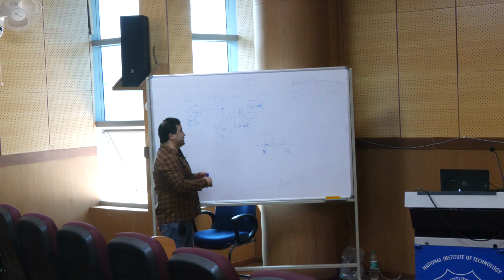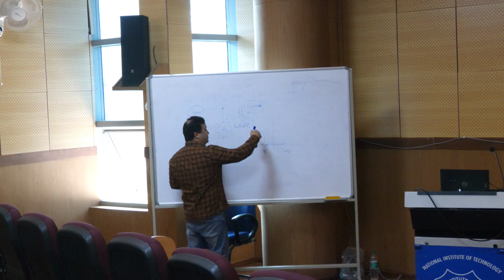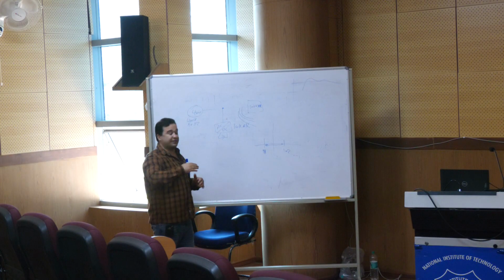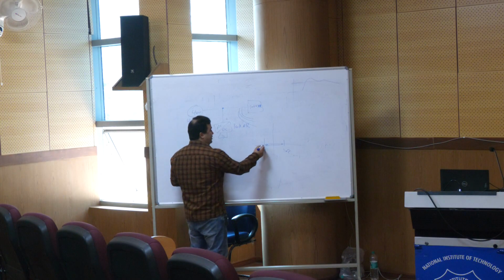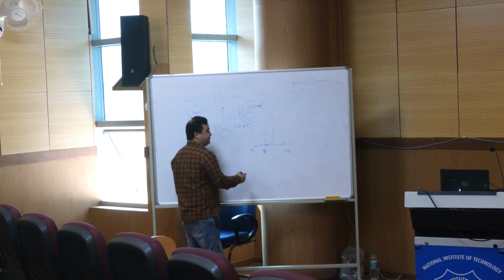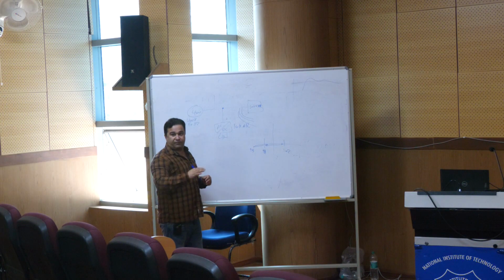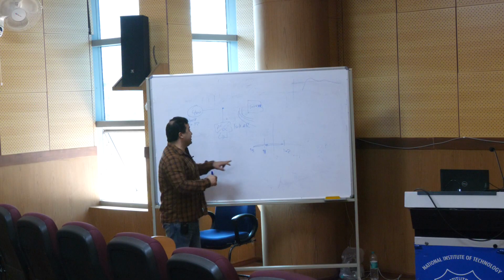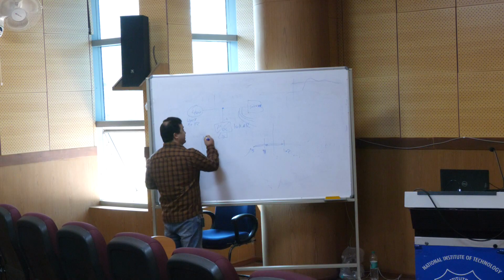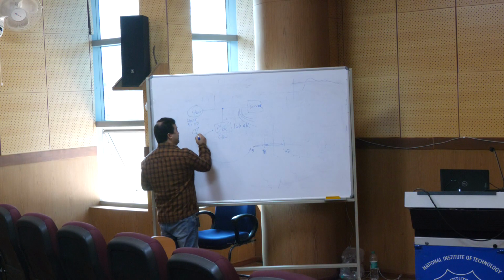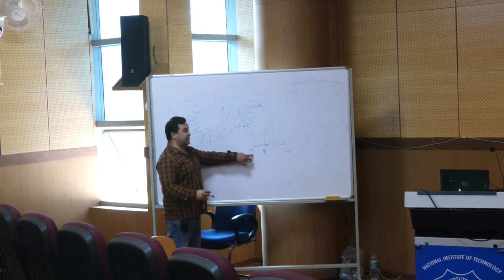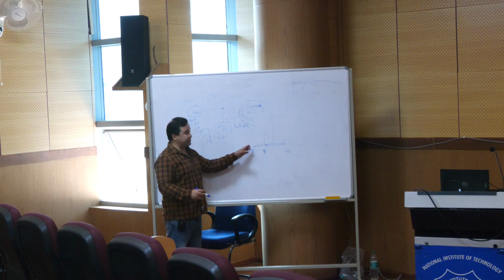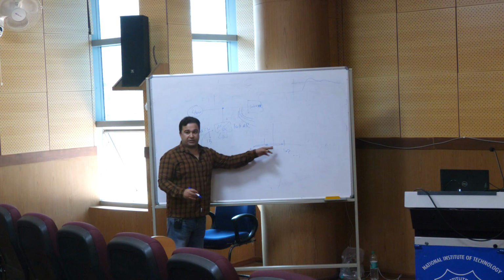But when we increase the reactive, for example, two times or several times more, then the voltage goes to, for example, 95. It drops 5% instead of 2%. So we need to update the reference from 10 to 15, or whatever value we need to compensate and return back to this operating condition.